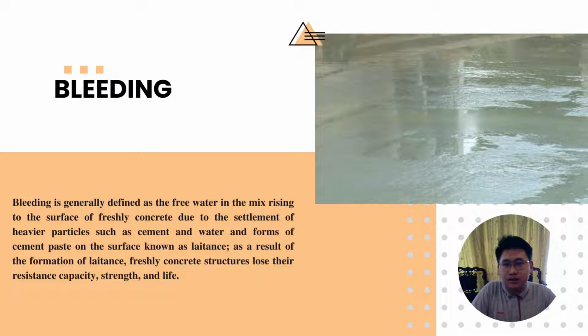due to the settlement of heavier particles such as cement, and the water forms a cement paste on the surface known as laitance. As a result of the formation of laitance, fresh concrete structures lose their resistance capacity, strength, and life.